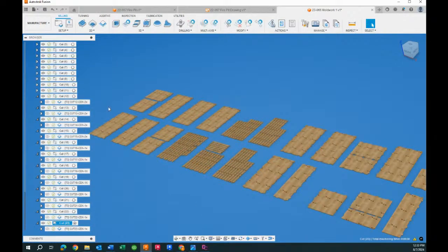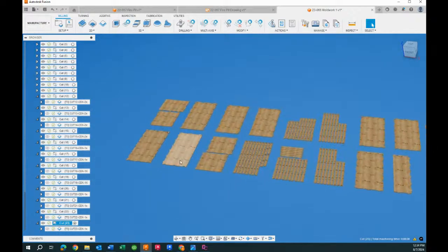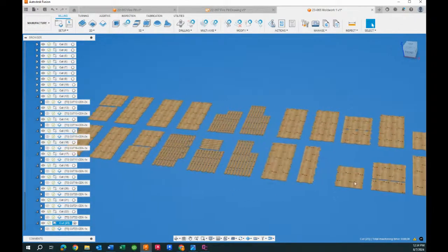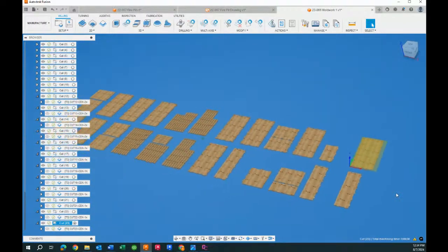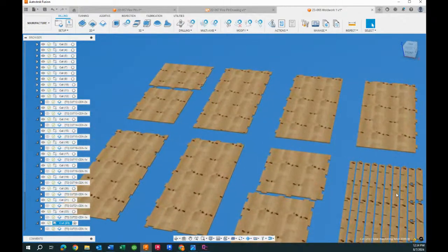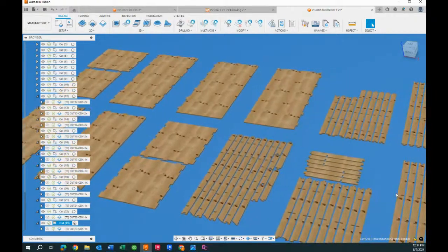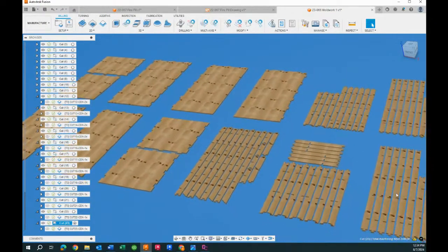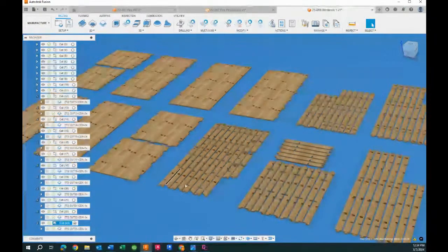I now have a common setup that we would then go through and define how we're going to cut out each sheet of plywood for this particular formwork. So you have more control over your spoilage of your material, more control over the efficiency of it, and more control over understanding and labeling individual parts and pieces, doing it out of 2D when you get larger forms, if that makes sense.